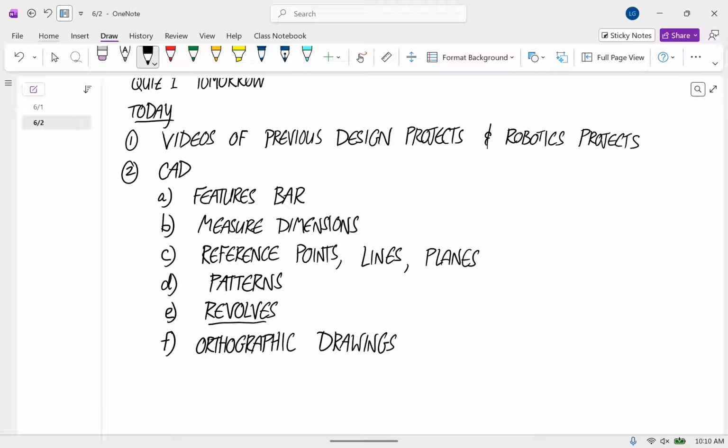It looks actually like, as I look at this, I should have... in the view that looks like this, it doesn't look like there's anywhere where I gave a height of that shape. So there should have been a dimension here showing that this height was 0.4.